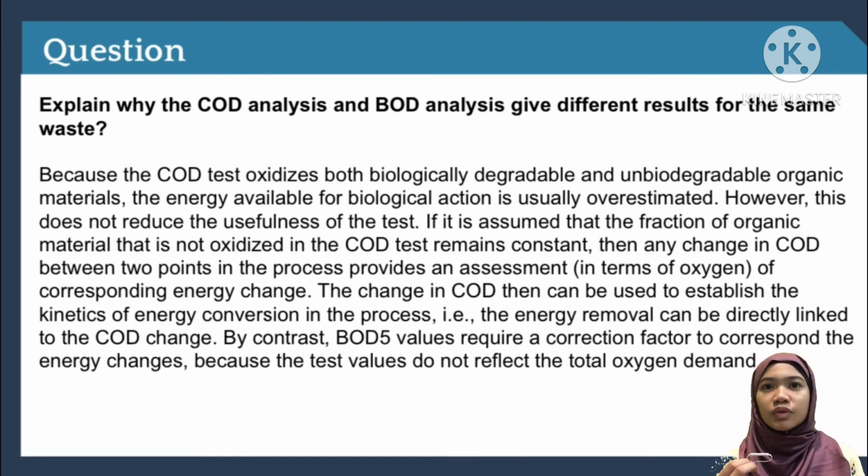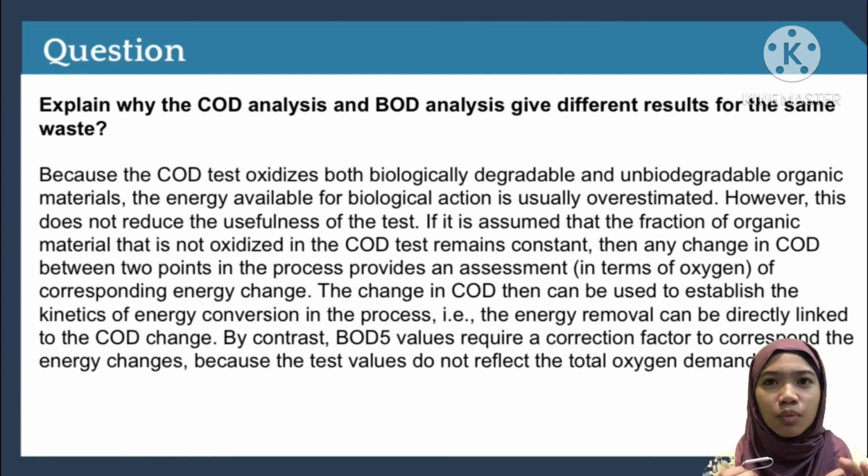However, this does not reduce the usefulness of the test. If it is assumed that the fraction of organic material that is not oxidized in the COD test remains constant, then any change in COD between 2 points in the process provides an assessment, in terms of oxygen, of the corresponding energy change.